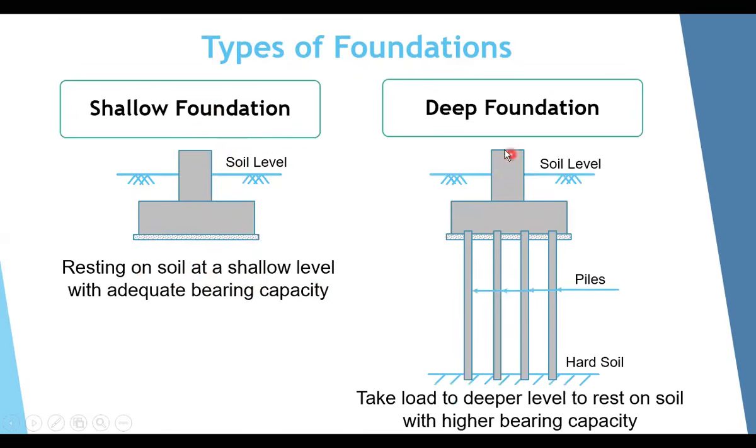We have to go to the deep foundation, where we can use piles, for example, to transfer load from the weak soil close to the surface to a deeper level of soil with higher bearing capacity. So in this case, the soil will be able to resist the load from the building. In this video, I will concentrate on shallow foundation.